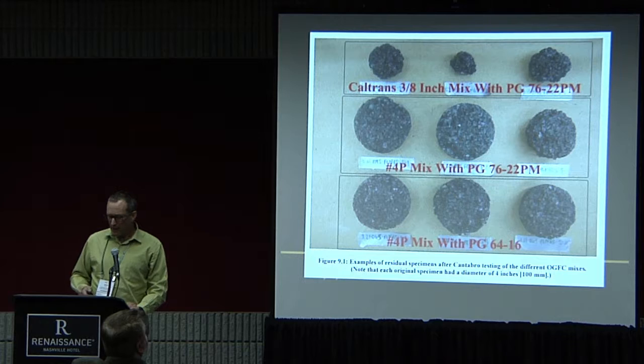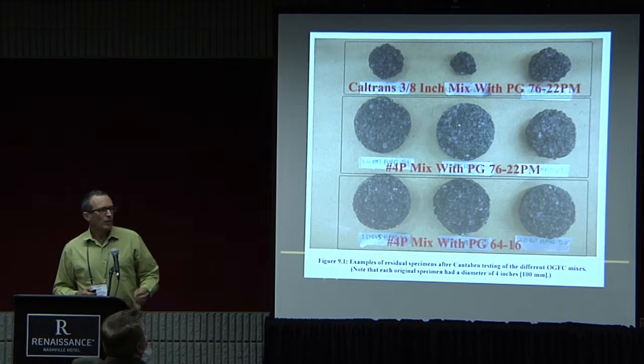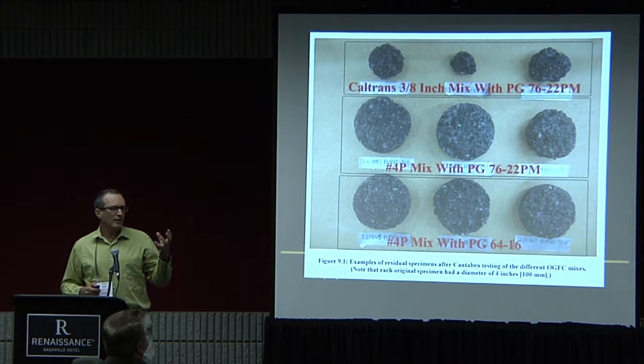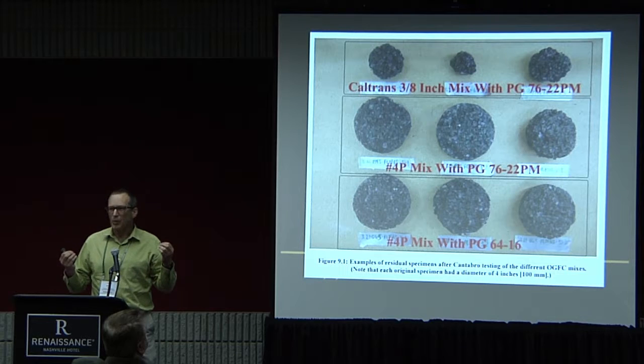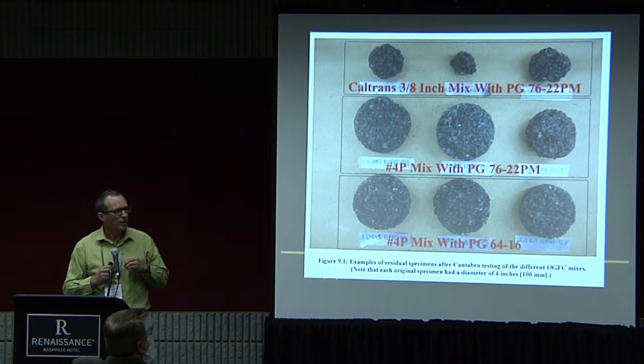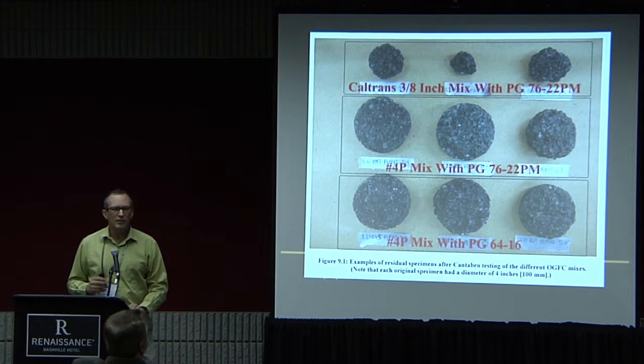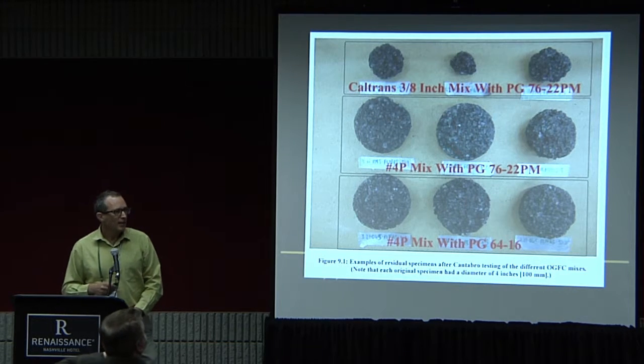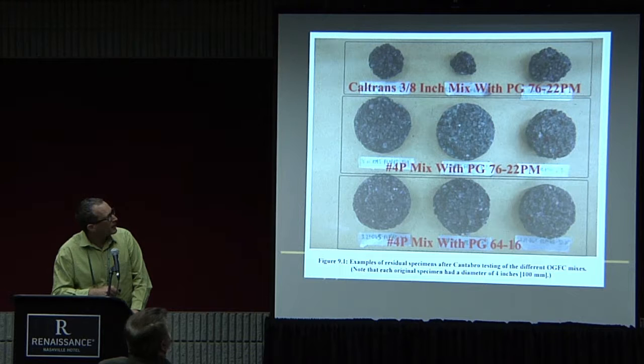Now, in terms of durability, we were also surmising that you have far more contact points. Open graded fails at those few contact points between the stones. So we threw these in a Cantabro device in our laboratory study looking at these mixes, and here's our traditional mix. I can't remember the exact reason. I think these are just replicates, and we put them in size order.